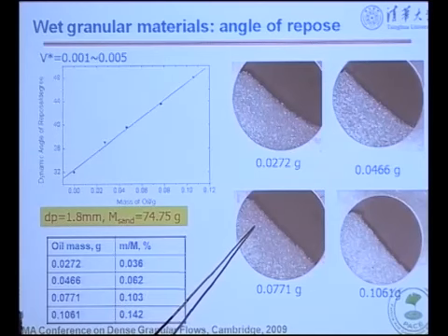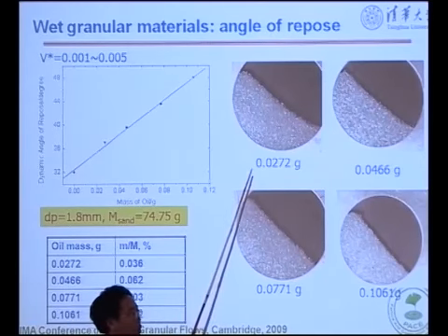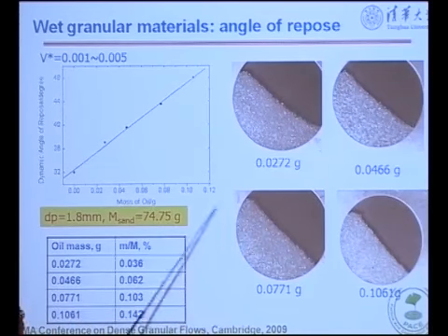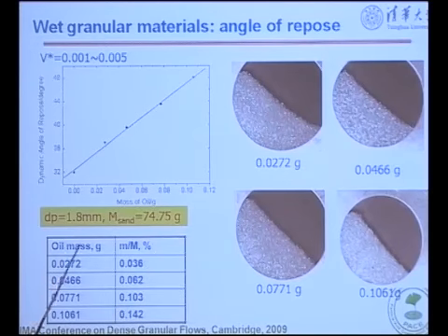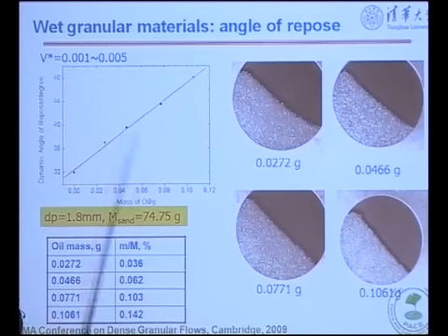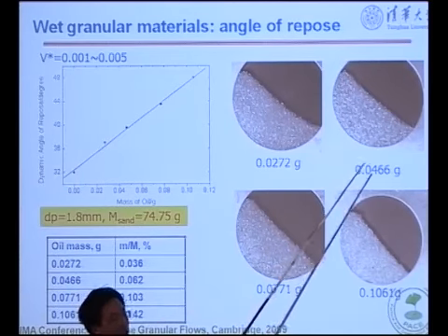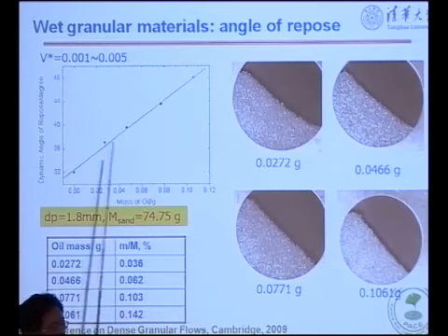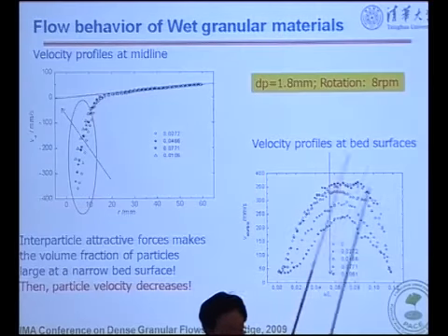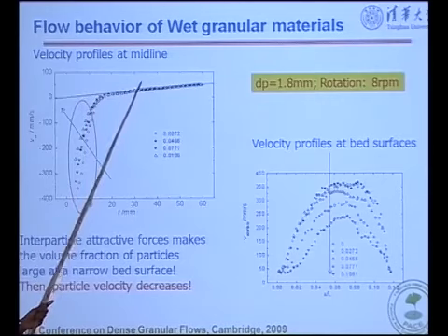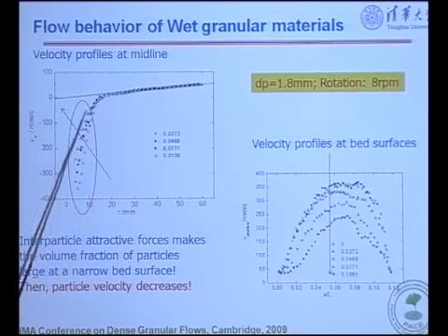And then, because today's topic is focused on wet material, we just add the total sand here. I calculated about 10,500 particles in the drum. And if we add silicon oil into it, we can find the angle of repose changes. It increases like this.